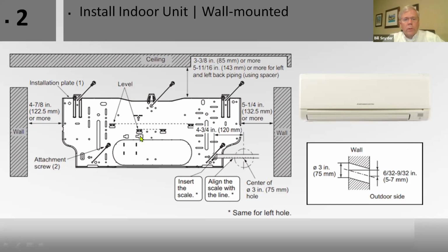These two flares on here tell you where that line set will be when you hang this on the wall; those lines are going to be right there at that spacing. So if you're bringing a line set from outside through the back, through the wall, through the side, through the bottom, you can make your flare right here and here.